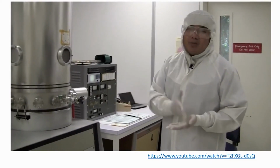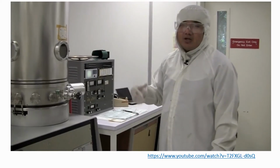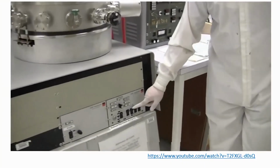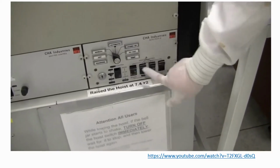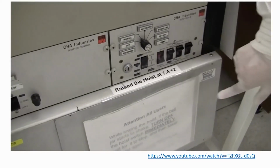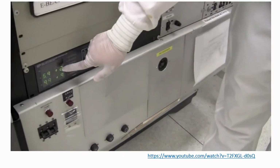But we can't just jump there, so we need to rough it with a mechanical pump. So the first thing we're going to do is turn the mechanical pump on, which is called a roughing. So there's a roughing valve here. And we just turn it on. Make sure the high vac and the vent is off. So we turn the roughing on, and you should see the pressure decrease.